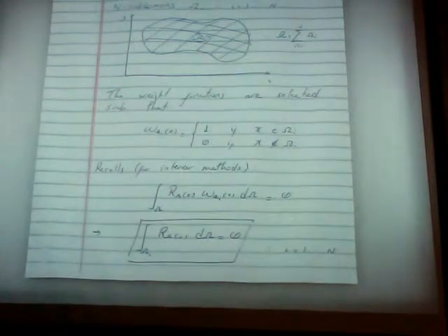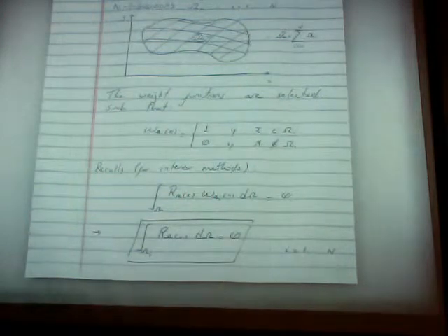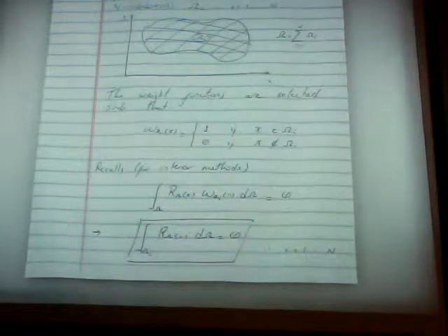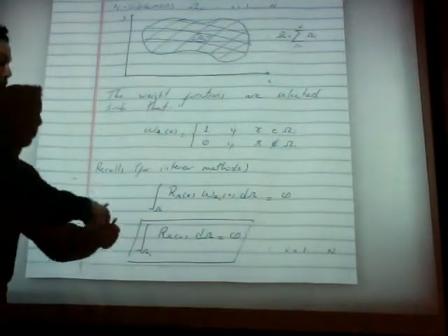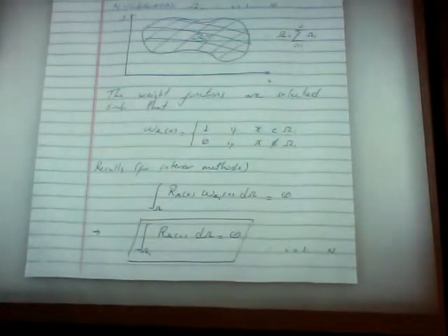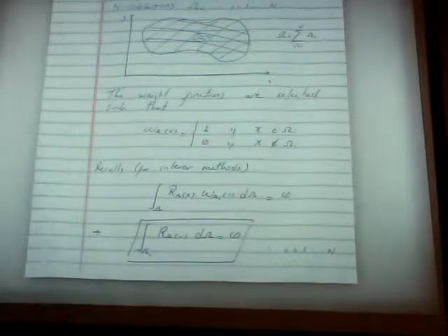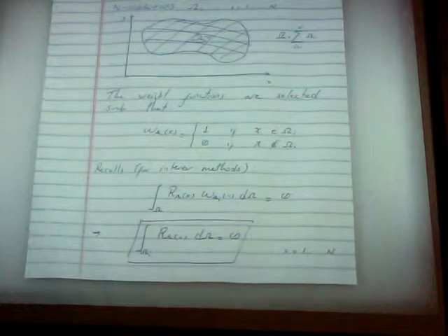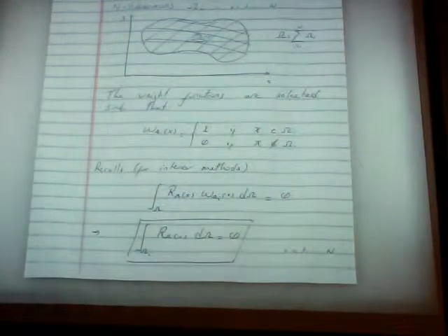But we have to carry out the integral. Now in previous collocation techniques, the weight function was the Dirac delta function, and therefore the integral disappeared. The integral went away. Now the integral stays, and we have to deal with it. In 1D, it's easy to deal with an integral, especially if the residual is made up of an approximation that includes polynomials or whatever. We can always integrate polynomials with no problems. But when you go to 2D or 3D, then you need to worry about how you are going to conduct these integrals, and that's why you introduce shape functions that are integrable and so on.